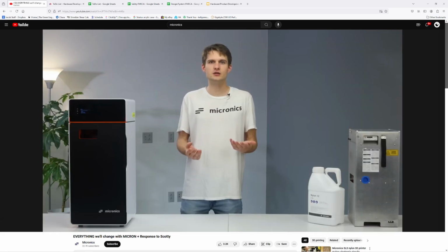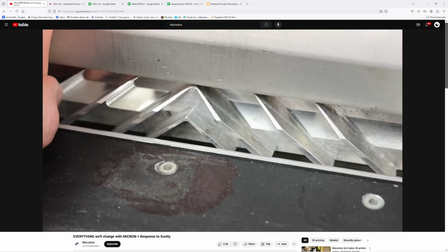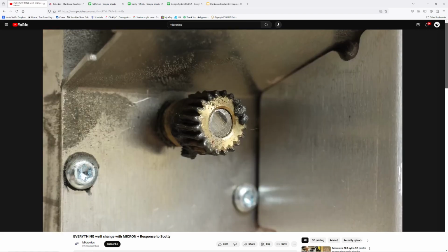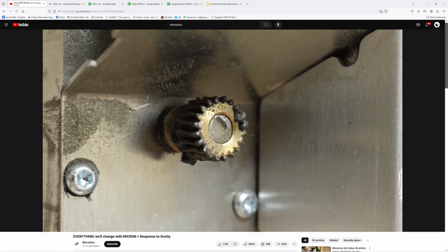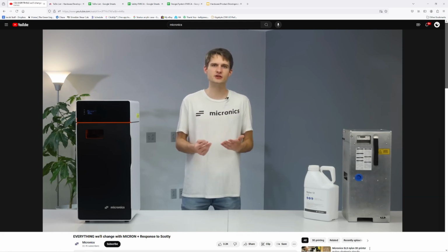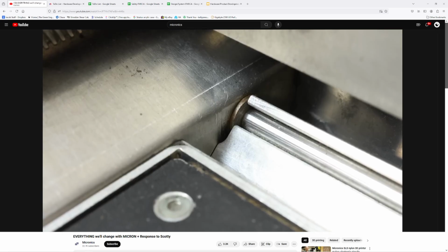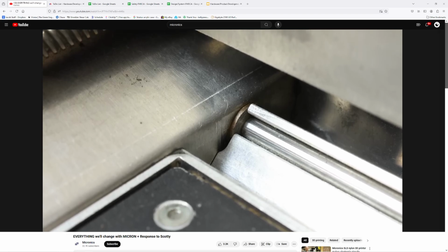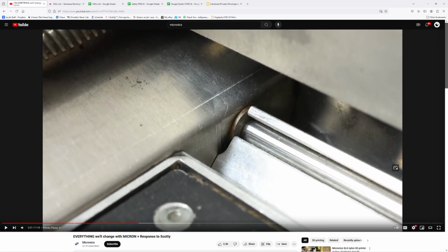Here's how it works. The auger lifts powder, which is then evenly spread across the width of the build area by the flipper's rotation before being lifted to the build surface. When we first noticed recoat failures, our gut reaction was to blame the gear driving the powder flipper, thinking it was skipping. But digging deeper, we uncovered a sneakier issue. During longer print jobs, some powder particles were getting in between the shaft and the bushings, causing the flipper to bind and fail.